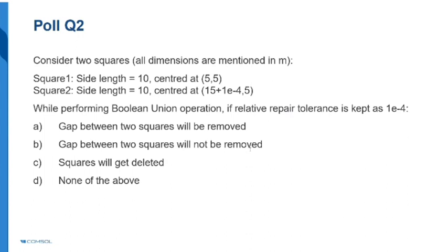There is one question: how is mid surface different from 2D? In this case, you are working in a 3D environment and you are creating a shell out of that in the 3D environment itself, and hence that is how I would say it is different. There is one more question: can we have move and rotate operations for the array objects? Yes, you can. You can first move and after that also rotate, or vice versa. Both options are available.